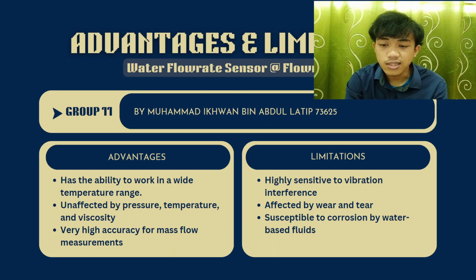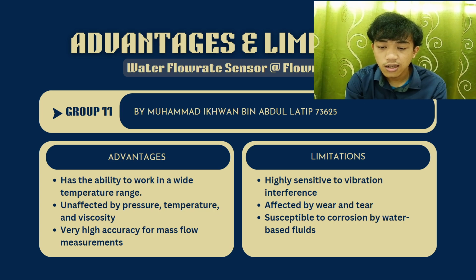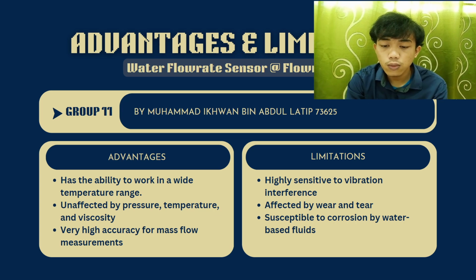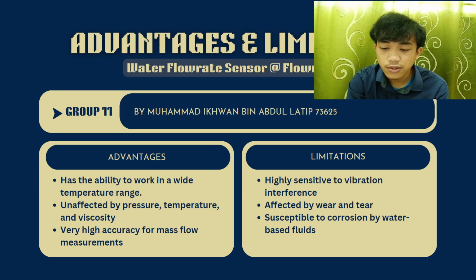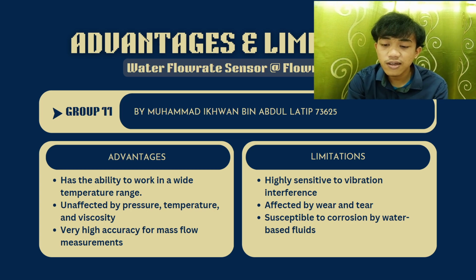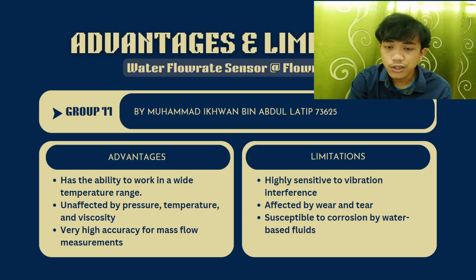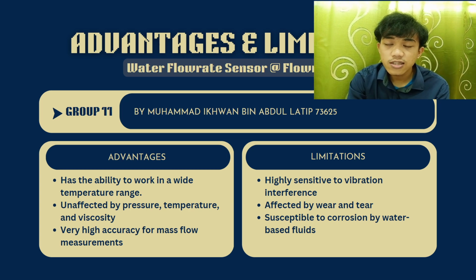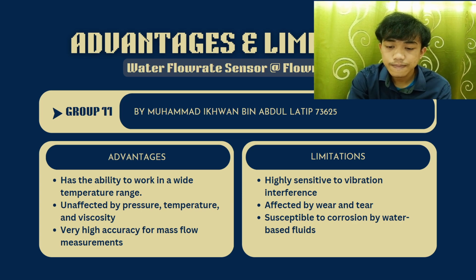For the water flow rate sensor, the advantages are that it has the ability to work in a wide temperature range. It is also unaffected by pressure, temperature, and viscosity of the fluid. It also has very high accuracy for mass flow measurements.